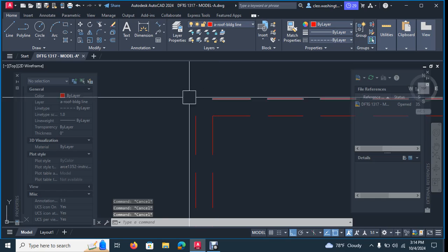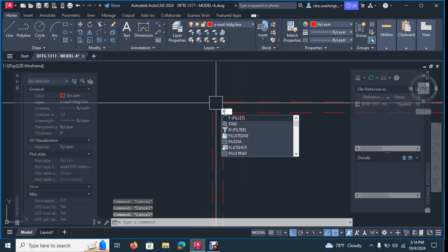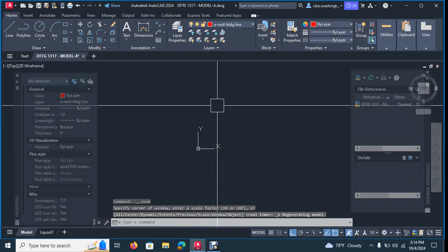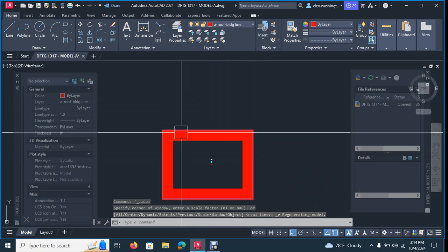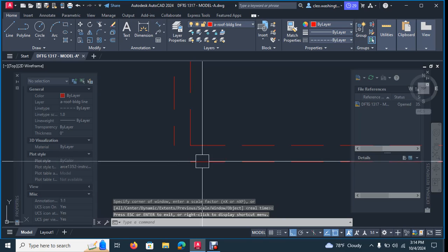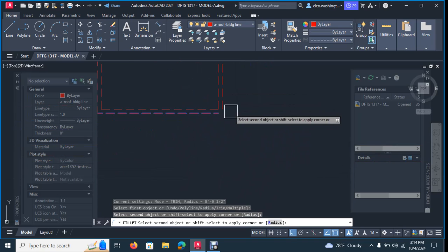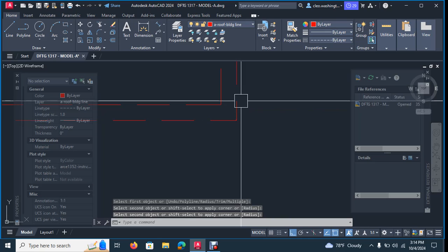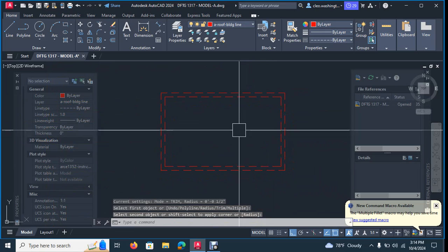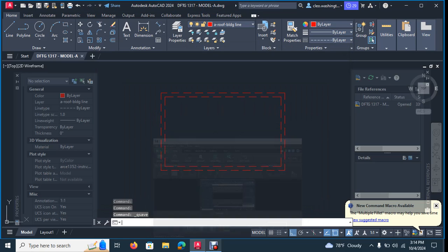And there is a command called fillet. If you type in F, you can click here and click here, okay? Then hit the F command again, hit the spacebar to activate it again, F, click here, then click here, click here, then click here. And then you want to click here, then click here, okay? Now let me do a save right now because I actually need to make sure my volume is still working. Okay, yeah, volume's still working fine.